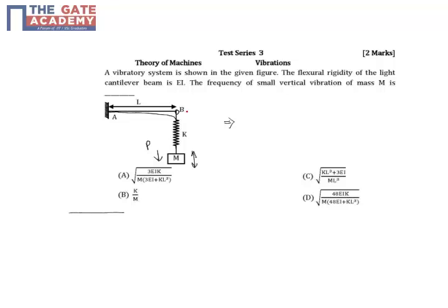So I can more or less consider, at this point B, the beam as a spring which, on the application of load P, deflects by as much as the beam would deflect. So the summary is that the beam can be considered as a spring, and there is a spring already attached, which is K. So these two springs are in series, sorry, not in parallel. And you should understand this series arrangement from how the load is applied.